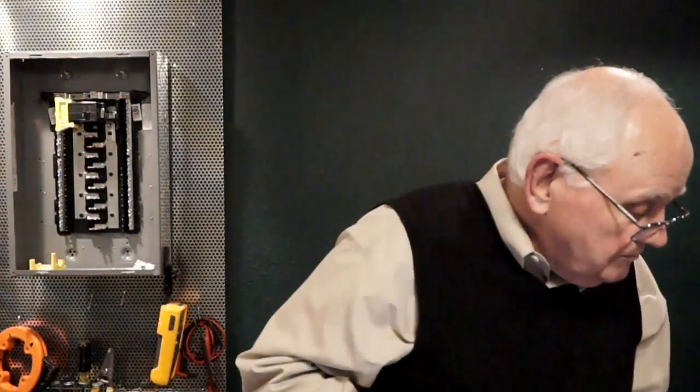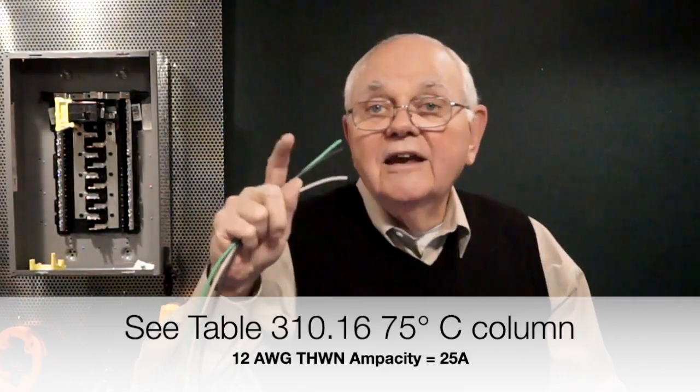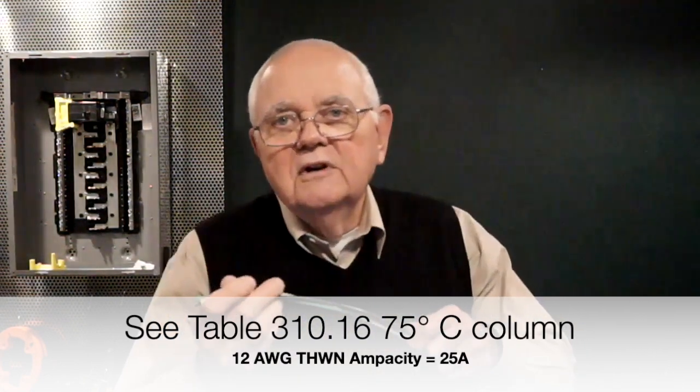Anyway, so at the 75 degrees C column, for using my conductor as a THWN, thermoplastic, 75 degrees C, H for heat resistant, and then N means nylon jacket, it tells me that the ampacity of this conductor now drops to 25 amps. So now if I were going to go back and do my adjustment and correction factors, I wouldn't be starting at 30 amps, I would be starting at 25 amps. So you can see I could end up with a lot lower allowable ampacity.